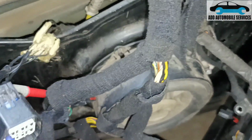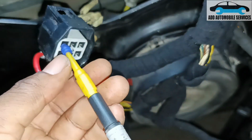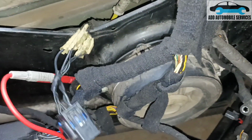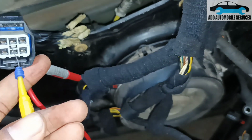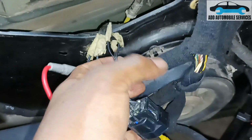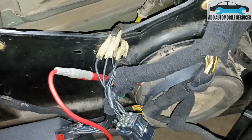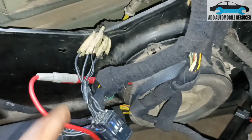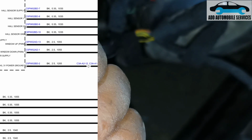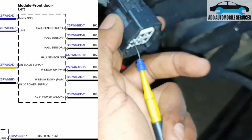So what I've seen is, when I check the wiring diagram, pin 3 goes with pin 7 on this. Now I'm on pin 7, but when I come here, pin 7 is rather on pin 5, which is wrong. So I will change the connection that was done here. I'll swap the connection, then I'll continue the diagnosing. So let me finish with pin 7 first. So now I've joined pin 3. When I take it out from pin 3, it starts beeping when I place it in. So I've done pin 3.